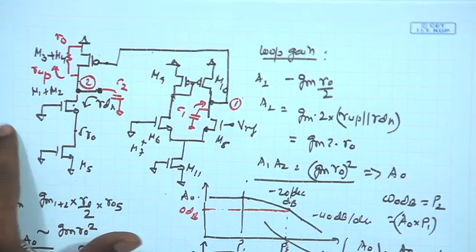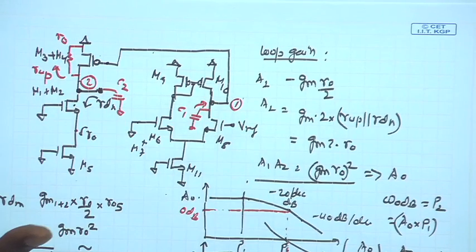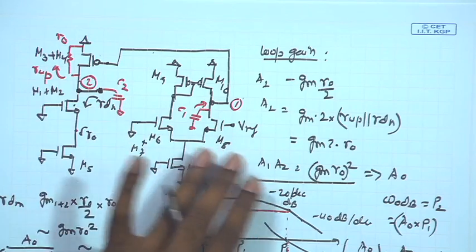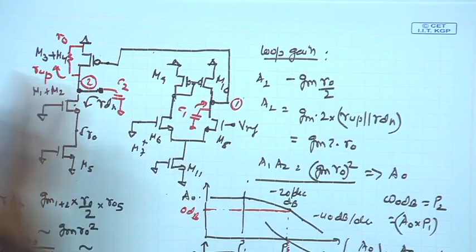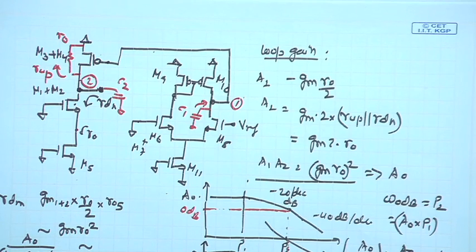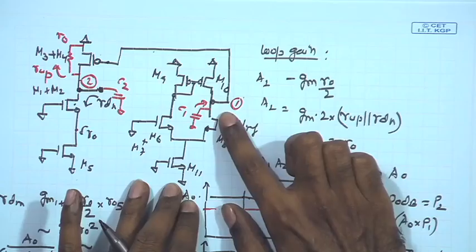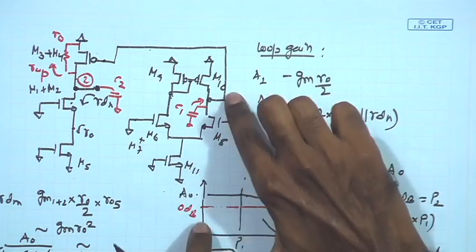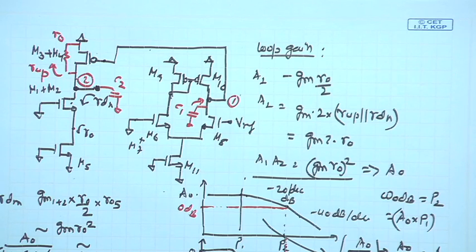As we have seen earlier, one of the common methods to achieve such splitting of poles, or pushing of one of the critical poles towards low frequency, is the Miller effect. So, we can intentionally add a capacitance between two circuit nodes, so that at one of the circuit nodes the overall capacitance, because of the Miller multiplication, becomes too high, and as a result the pole at that particular node is pushed to very low frequency.